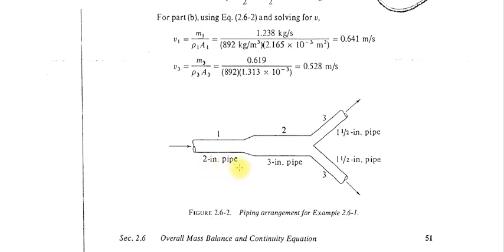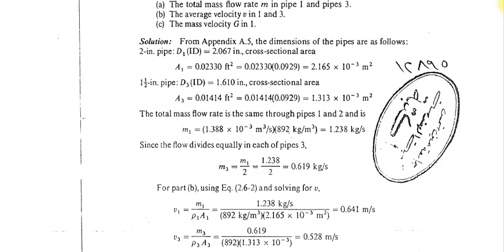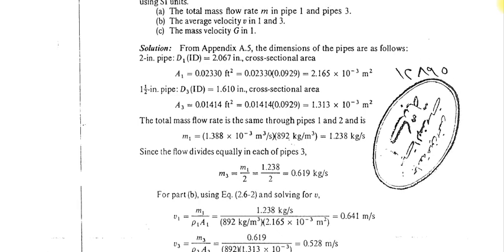So this is the 2-inch pipe. This is the nominal diameter. This is not the outer diameter. This is not the inner diameter of the pipe. This is the nominal, that is the average of outer and inner diameter. Then you have to write the schedule number. The schedule number defines the thickness of the pipe. When you see the schedule number charts, you can calculate the internal cross sectional area directly. So here the cross sectional areas are already given.